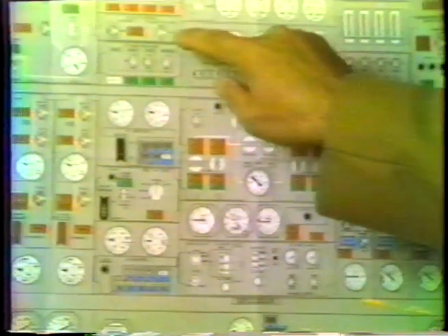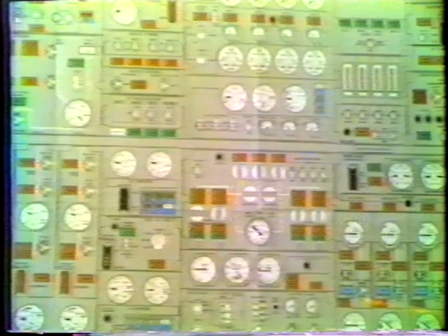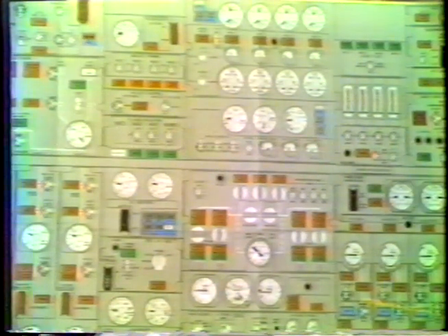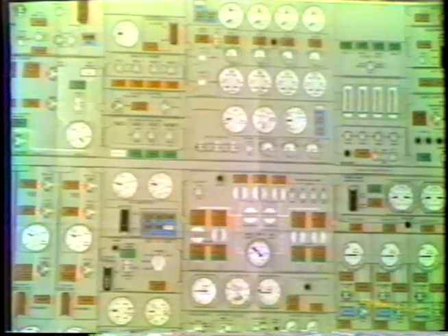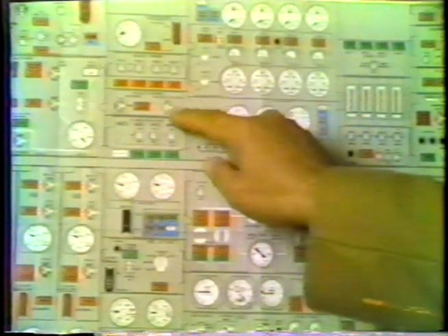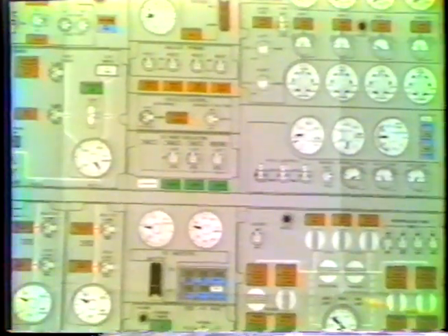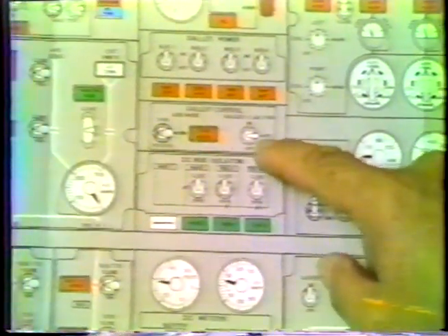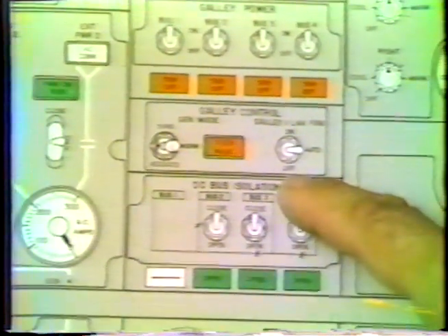The vent system is exactly what it says. It's to remove odors from the galley and the lavatories when low pressure differential is in the airplane. So on the ground and at low altitudes it's operating all the time. If you wanted to operate at higher altitudes, you can take it out of auto and put it on, and the vent fan will operate under all conditions regardless of the pressure differential. Likewise, by moving the switch to the off position, you will turn the Lav galley vent fan off and it will not operate at all.